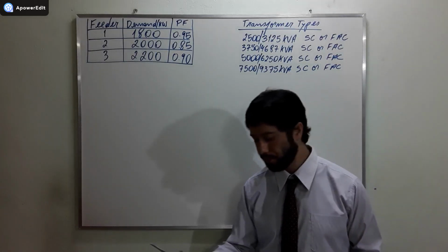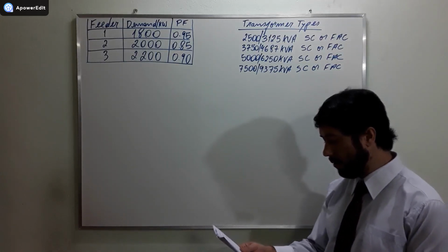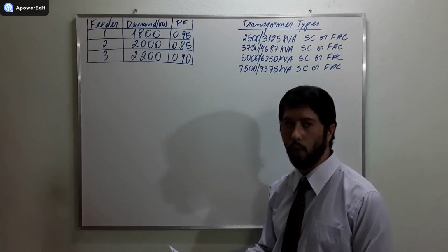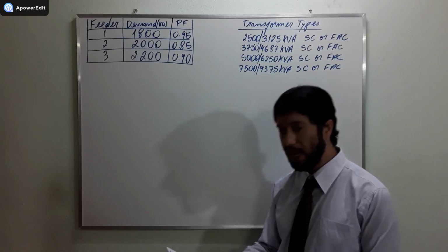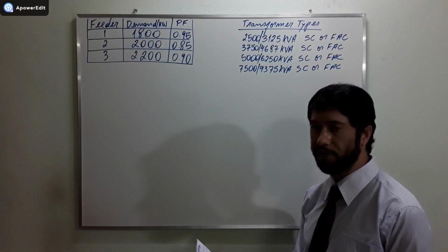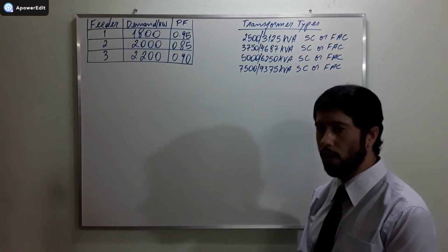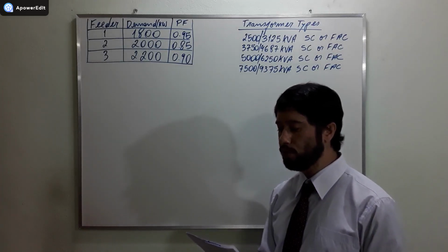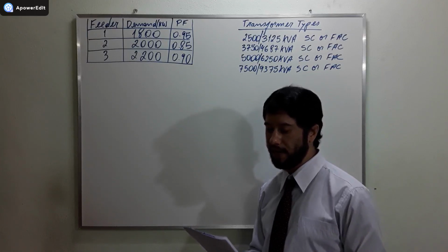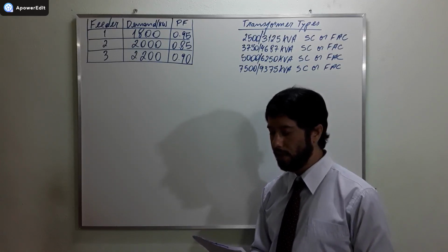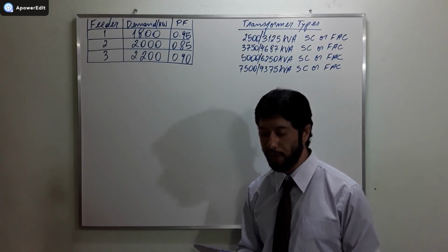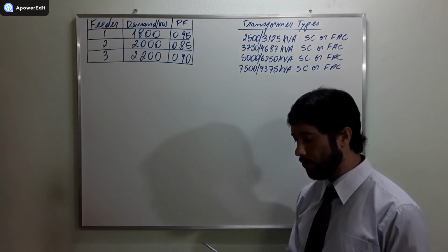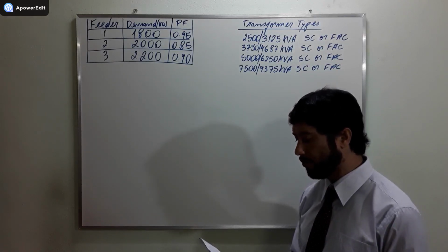Letter A, calculate the 30-minute annual maximum demand on the substation transformer in kilowatts and in kVA. Letter B, find the load diversity LD in kilowatts. Letter C, select a suitable substation transformer size if zero load growth is expected and if the company permits as much as 25% short time overloads on the distribution side of the substation transformers.